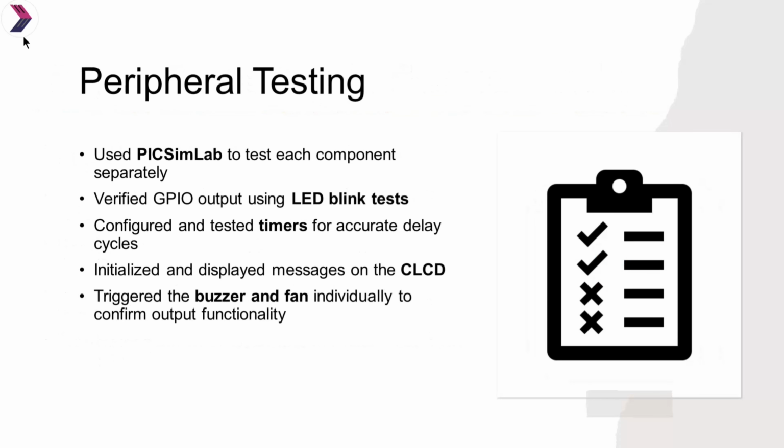Then peripheral testing. Use PICSimLab to test each component separately, verified GPIO output using LED blink tests, configured and tested timers for accurate delay cycles, initialized and displayed message on the CLCD, then triggered the buzzer and fan individually to confirm the output functionality.